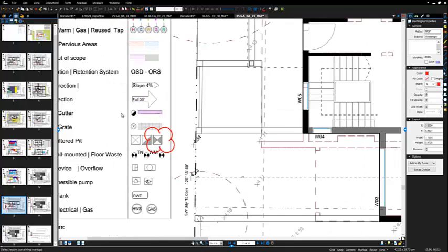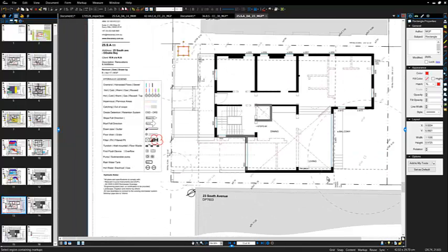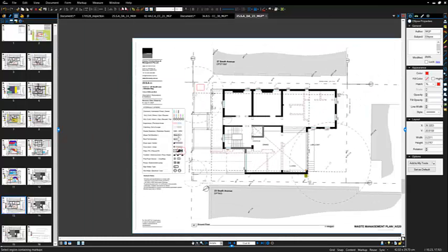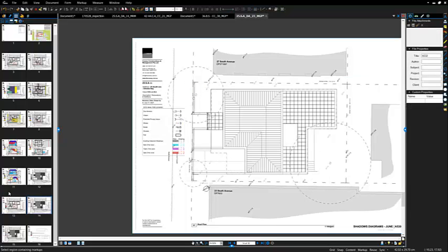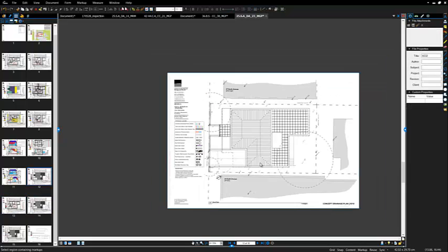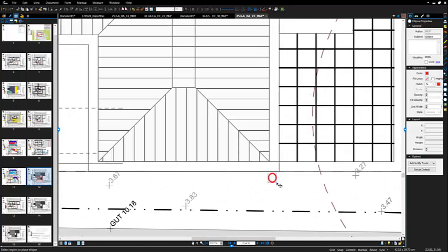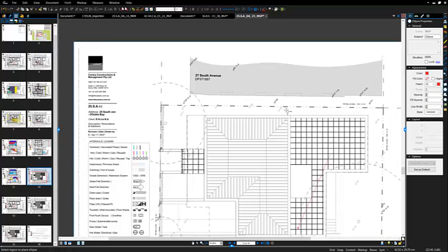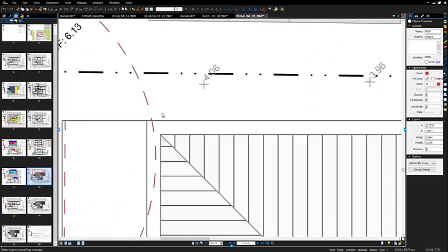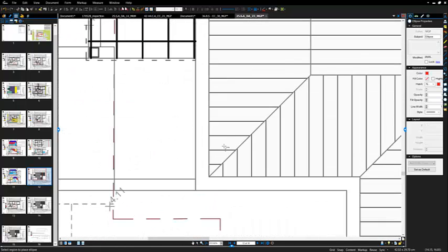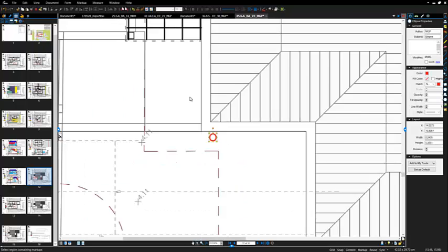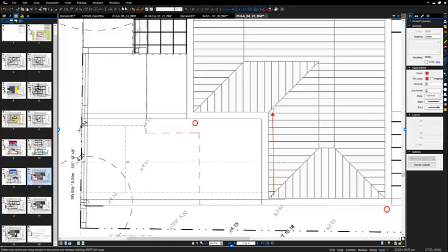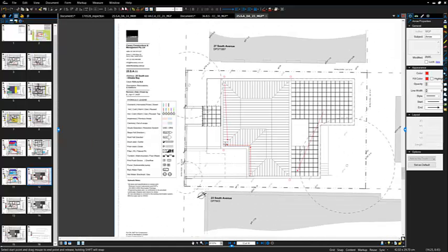So we just do the down pipe, it is one. We should put one here. And let me go to the waste management. This is the shadow diagram. This is waste management. This is concept drainage plan. Okay, so one would be here. So we have water coming from here into this point, and another one we're gonna have here, and another one here, and another one here. Yeah. So then we show with arrows that the water will go like that, because it's a special roof.